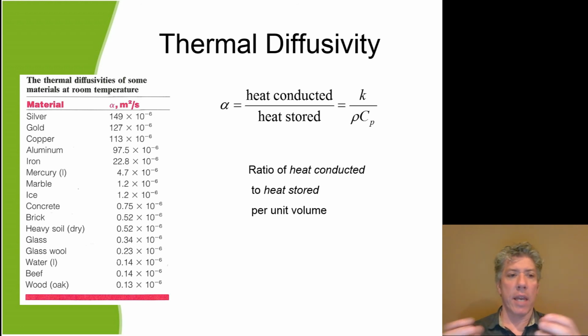If you think about a big hunk of aluminum, that's kind of like an empty container just waiting to receive a fill of something, right? A fill of thermal energy. And so the aluminum, assuming that it has a decent heat capacity, could absorb that energy, but eventually what's going to happen is the temperature of the aluminum block will rise and the heat won't be able to get out of the LED, or the thermal energy won't be conducted away.